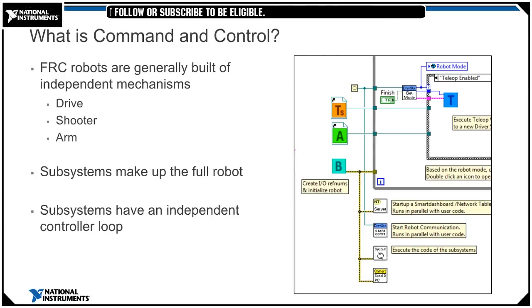This really speeds up debugging a misbehaving robot because it gives you the ability to look back through the list of commands you sent to each subsystem rather than searching through your project where you might have modified that one output, but it could have been in this VI or that VI. It also becomes a lot easier to add an additional sensor or change your gearing or disable a mechanism without needing to modify any code outside of that specific subsystem.